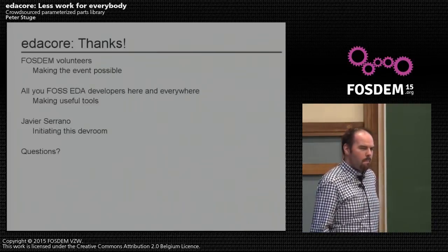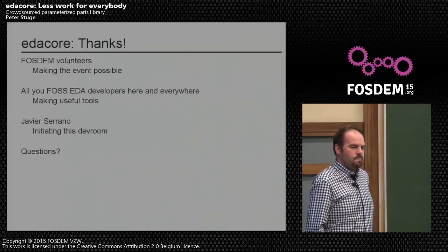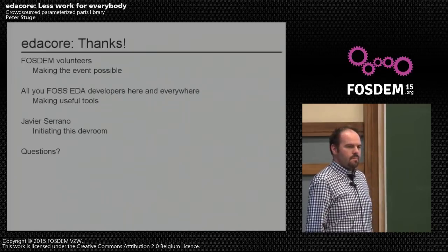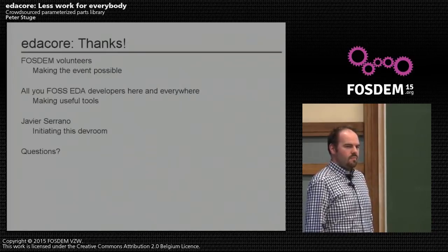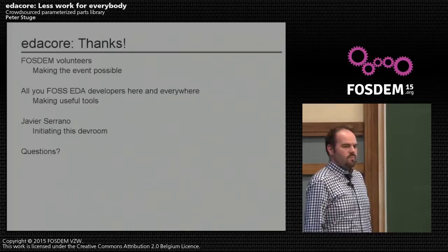Question? I came across a similar idea just from another direction. I want to take a schematic from somewhere and repair this board. So I need something like an instruction on how to start, which point to measure, and so on. My suggestion is to simulate different errors, stuck-at faults, bridges, shorts, and so on, on the board, get out the data, compare the data, and just build an instruction.